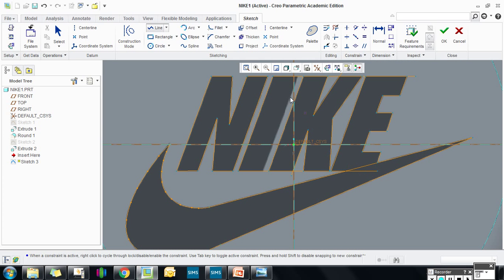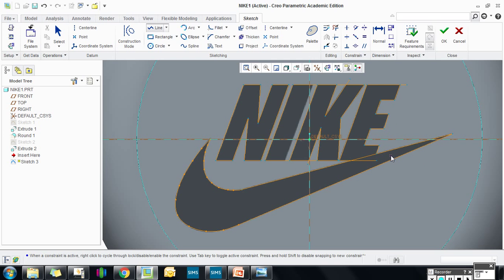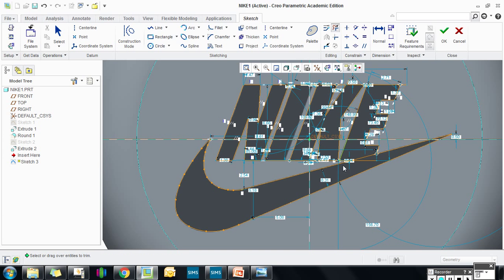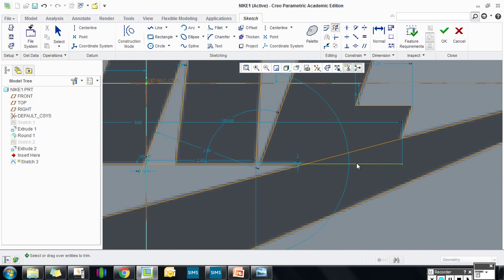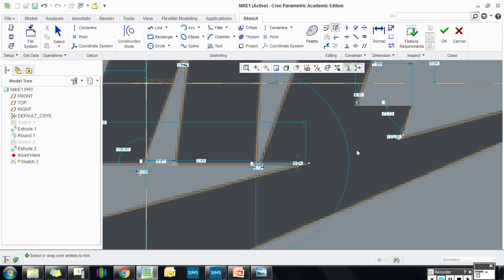Okay, I have most of the logo now drawn out, but what I have to do, this will not work. I cannot extrude this if I've still got lines overshooting or crossing over. It needs to be a closed shape. So I'm going to get the delete segment tool, and I've got to zoom in and delete some of the lines I no longer need, leaving me a closed shape. So between the letters there will be gaps.